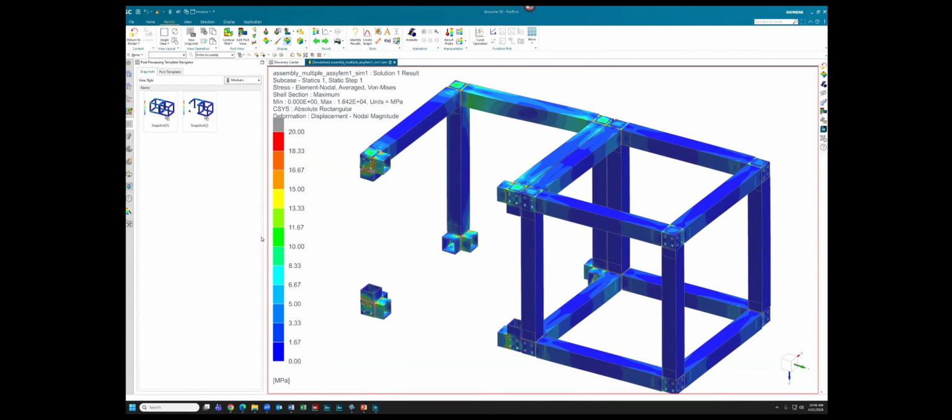So, an incredibly useful feature. This is something I am using every single time on post-processing. I use it a lot to define individual snapshots for individual components, such that you can get that really nice looking stress picture for an individual component. And you can do that for all of your components within your assembly. That's going to save you so much more time when you have to run additional load cases or design iterations. You can potentially already have all of those contour pictures ready to go.